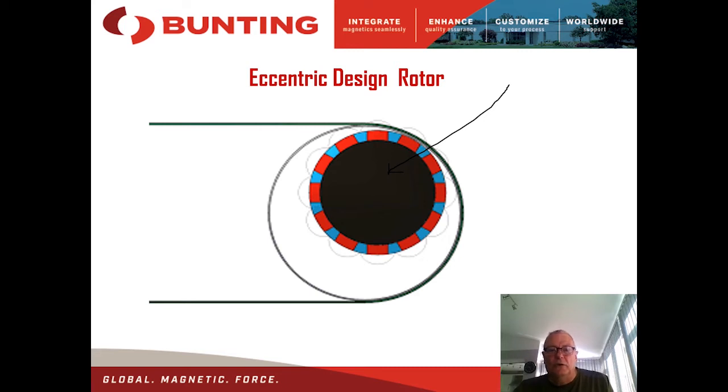First of all, it reduces the cost of the overall unit because we're using less magnetic material. Also, this smaller pulley configuration allows us to run at higher RPMs, which gives us greater force, which for some applications is very good. So it has process advantages there.